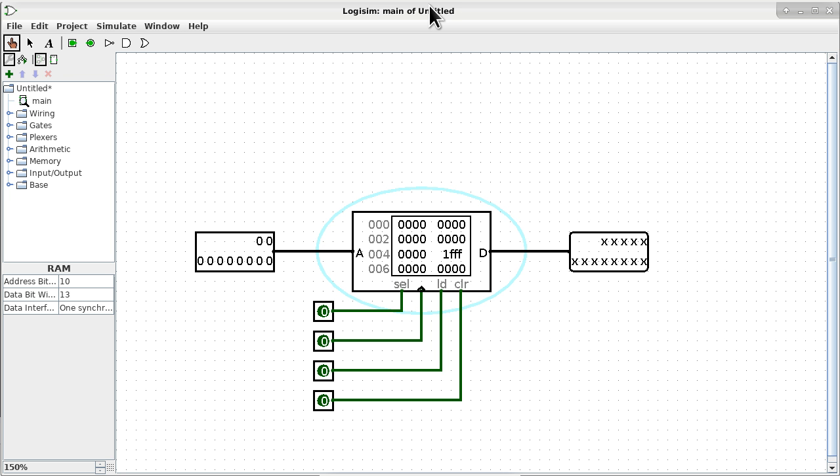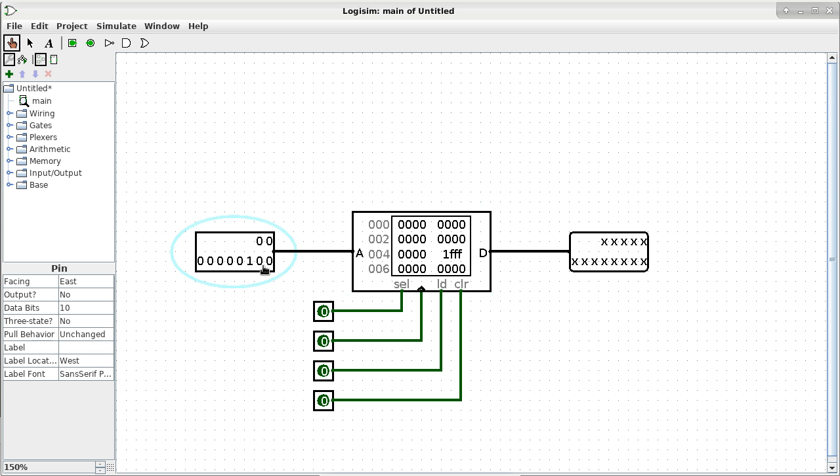Okay, what is 5 in binary? 101, very good. So all the most significant bits are zeros except for 101 as the least significant 3 bits, okay? But nothing is happening, why? Because the RAM component is not even selected. It's not paying attention, it is not enabled.